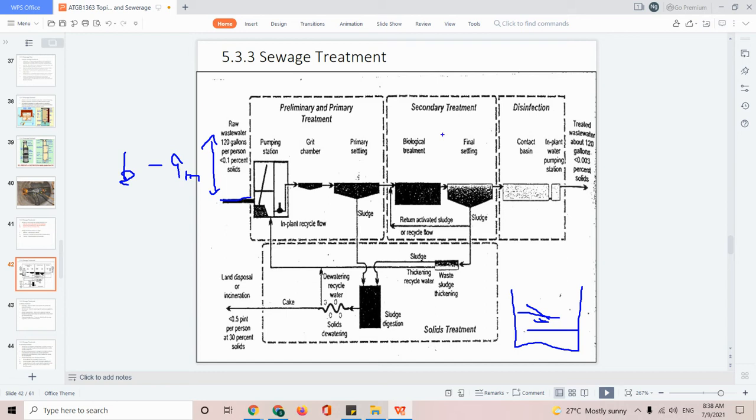So how many houses they need to be able to service? When it comes to a development, let's say a residential building, a sewage treatment plant is rated to service a certain number of people. From there, we are able to lay the pipe, or do pipe jacking, and lay all the pipe at a self-cleaning gradient towards this sewage treatment plant. First off, we'll end it at the pumping station.